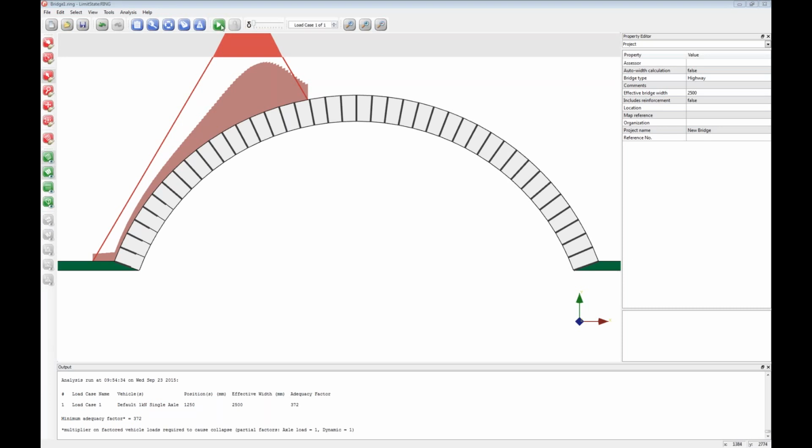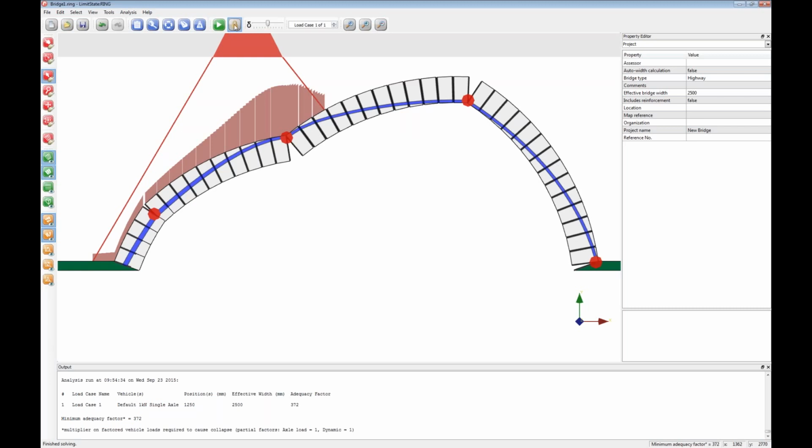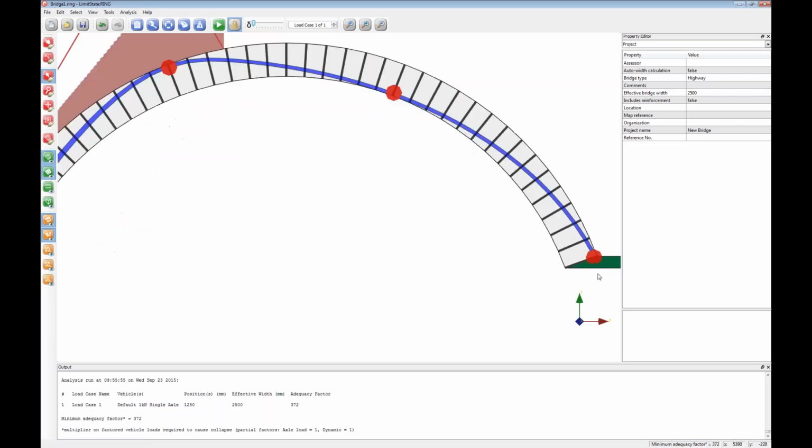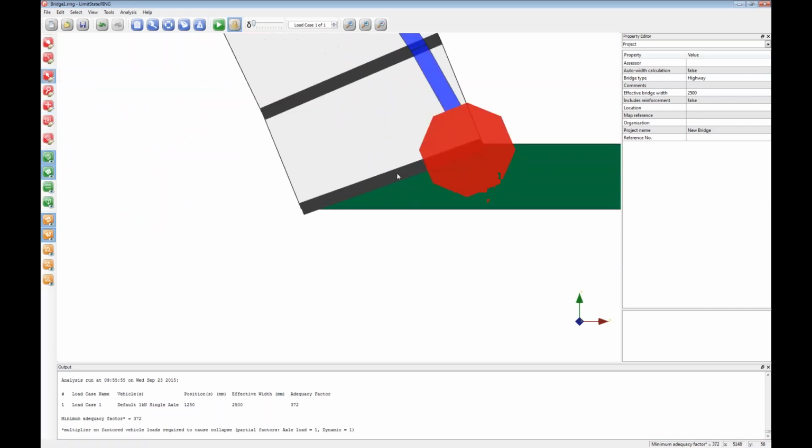Well, if I solve again this model and I click on the contact at the extremity of the bridge, then I will actually get a shear force and a normal force. So effectively that gives us forces which we can alternately express in terms of horizontal and vertical forces.